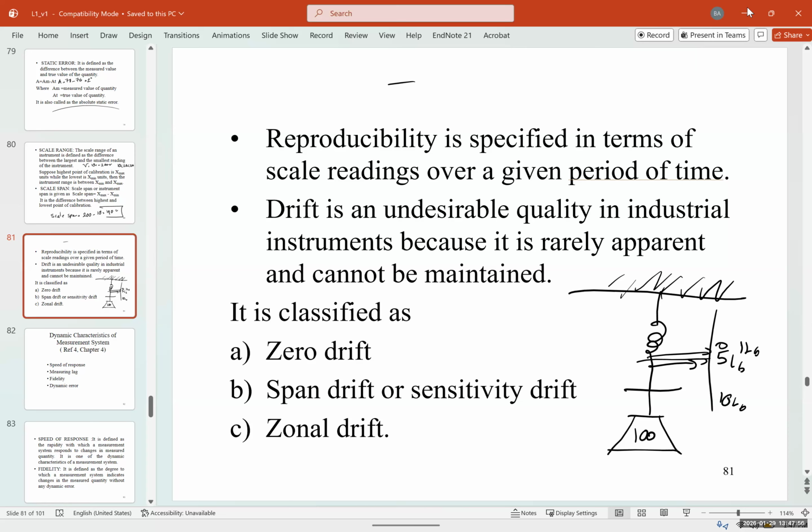And it happens a lot, especially in electromechanical sensors like a voltmeter. They have a spring, and the problem with these springs, when you use it a while, the spring loses its characteristics. It doesn't go back to 0. It stretches, and you put too much stress in it, it does that. So what you have to do, they usually have a knob on them that once in a while, you have to correct it and recalibrate it.